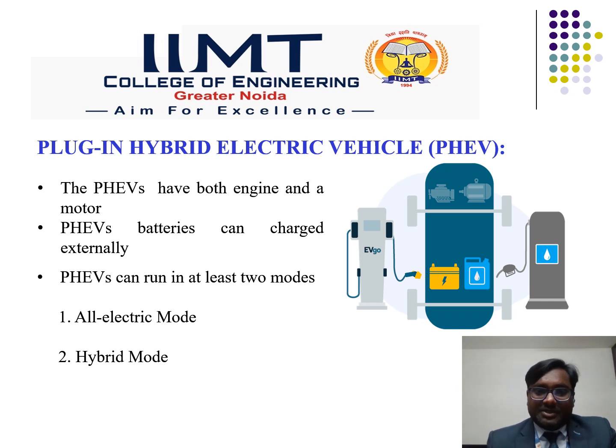PHEVs start up in all-electric mode initially and make use of electricity until their battery pack is depleted or drained. Once the battery gets drained, the engine takes over and the vehicle operates as a conventional non-plug-in hybrid. PHEVs can be charged by plugging into an outside electric power source, the engine, or regenerative braking. When brakes are applied, the electric motor acts as a generator, using the energy to charge the battery.